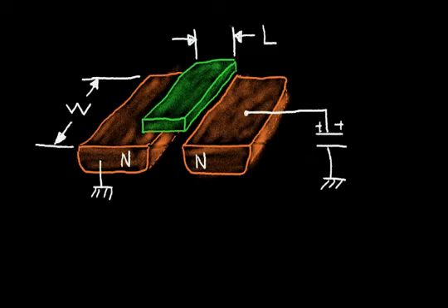So let's review the MOSFET operation just very briefly. When I raise the gate voltage relative to the source voltage, I form a channel region in this MOSFET transistor, and that causes current to flow from the drain to the source. Now the key thing I want to point out is that as I make this transistor wider, as I increase the width, I increase the region of the current flow from the drain to the source. And I can think of this channel region under the gate as a resistive material. So let's think of that channel as having an equivalent resistance that connects over to my capacitor with the bottom plate at ground.